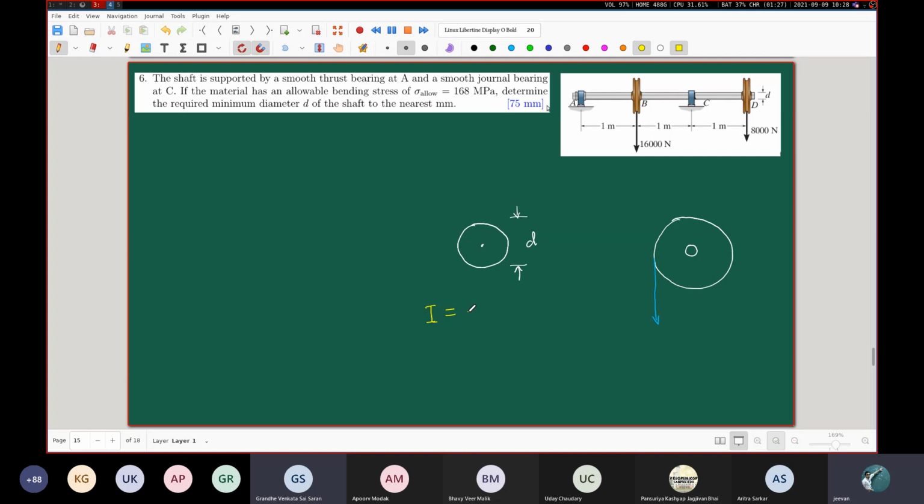Of course, we consider the general equation of the circle and double integration. Right, so that is always the generic answer. Given any cross section, you can of course find out the second moment of area by doing this integration of y squared dA. That is certainly true, but I'm sure you realize that that's not why I'm asking this. So we can consider rings of thickness dx or dr, whatever, at radius r.